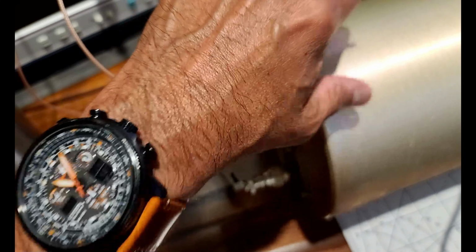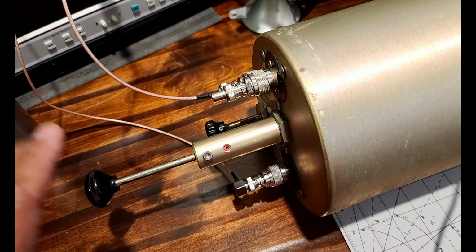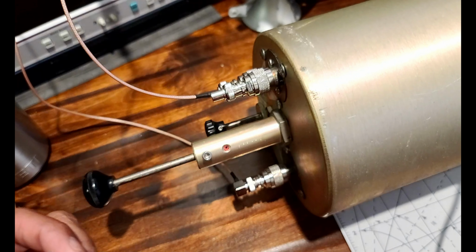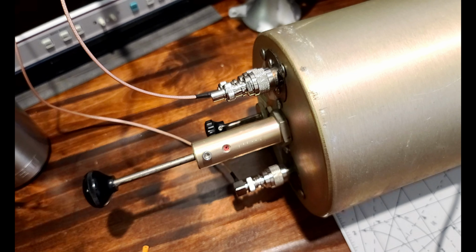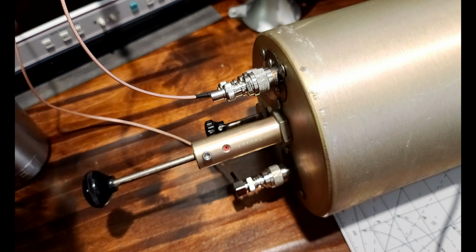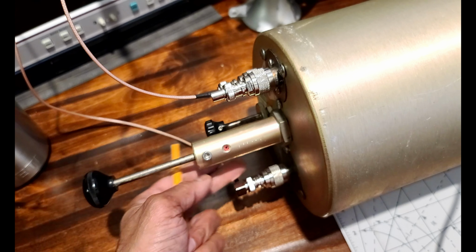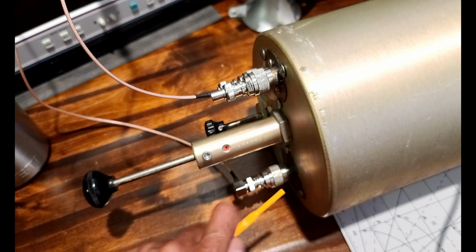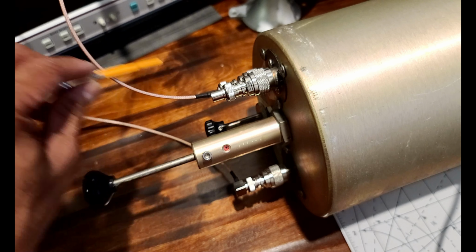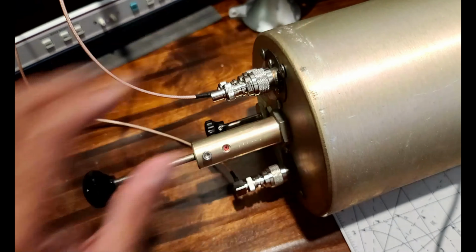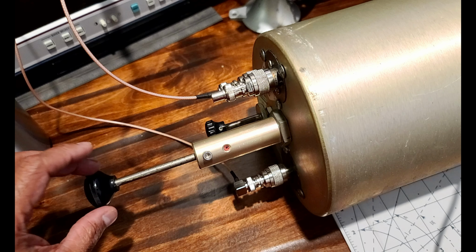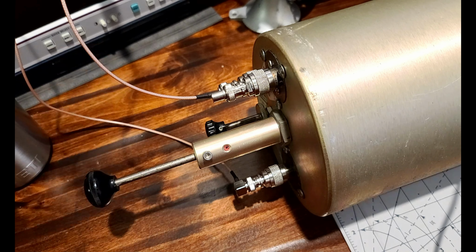So in my previous video, I demonstrated how I tuned this quarter wave cavity filter to the US APRS frequency, which is 144.39. We used the transmission loss method, wherein the output from my spectrum analyzer's tracking generator was fed into the input of the cavity filter, and then the output of the cavity filter was fed into the RF input of my spectrum analyzer. And then we used the frequency response graph to tune the cavity filter by moving the coarse tuning plunger and the fine tuning plunger to that frequency.